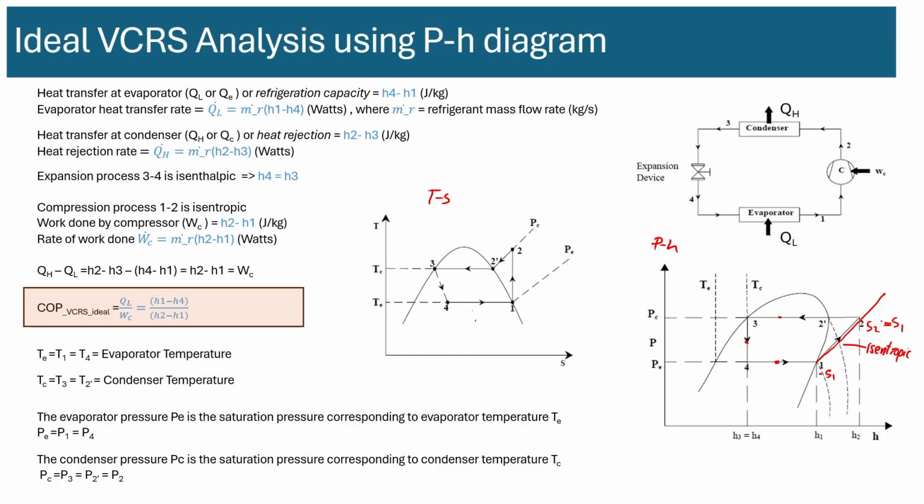And when you finish the compression, you exit at the highest temperature possible in the system. Okay. Now that compression is done, you have to cool that fluid in the condenser. So initially, you're cooling and the temperature drops. And when you hit this point, this is the saturation curve, or you can call it the vapor dome, right? So inside it is two-phase, and outside on the right side is vapor, and on the left side is liquid, right? So the vapor is superheated vapor, the liquid is subcooled liquid. That's another way to call it. And inside they have both liquid and vapor.